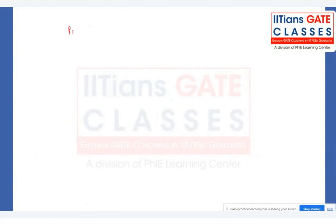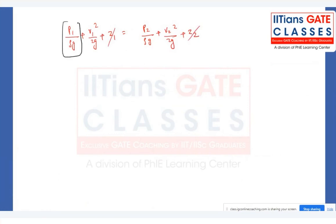So here, whatever Bernoulli principle we have applied: P1 by rho g plus V1 square by 2g plus Z1 equals P2 by rho g plus V2 square by 2g plus Z2. Z1 and Z2 are already cancelled out. And here, my dear friend, this P1 by rho g is the static pressure. Yes or no, guys? The pressure measured by the pitot tube is the stagnation pressure. Can we write that?